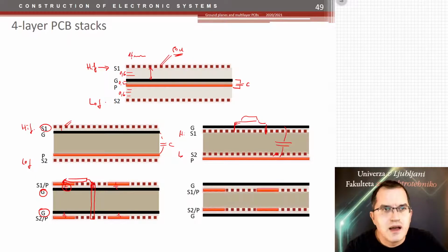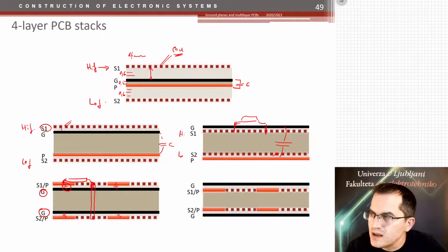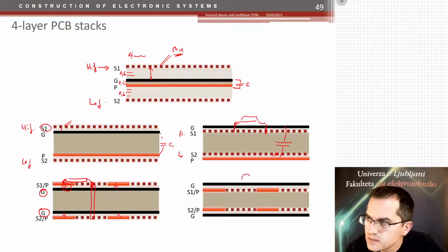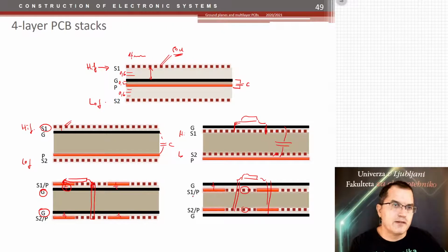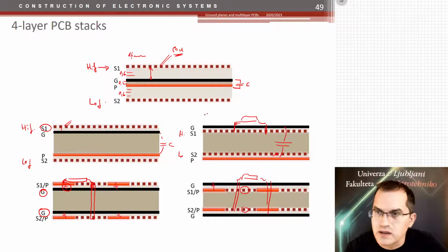And the last and the best there is would be using ground plane on top and bottom, having ICs there, and then of course you need wires for every single pin connecting, but you have really good capacitances there, you have very well defined impedances of these tracks, very low current loops, very good shielding, and I would say among all these 5 to make a verdict, that one is never used.